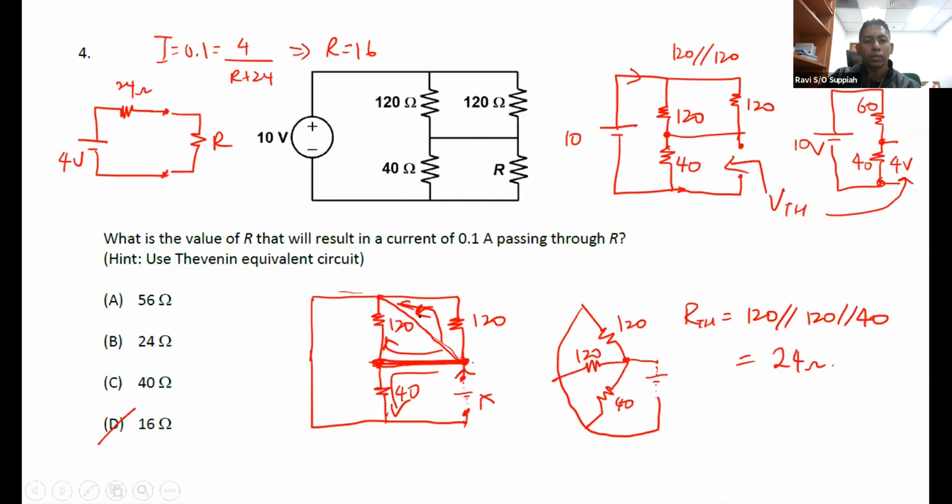It's a full short circuit path. Why? Because I have now created a pathway that directly connects the positive to the negative with the least amount of resistance because it's a short circuit pathway. As long as you don't have this, then you need to look at how the current will flow. The best way is, like I said, to redraw circuit connections so that if I have 2 short circuit points, I can redraw them as a single point.